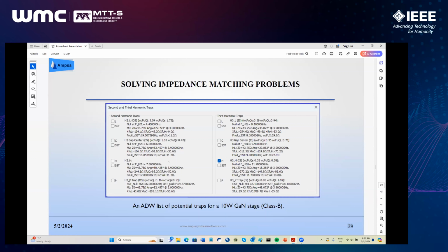So this is a useful table. I can at a glance say, I want to cover this frequency range. For that frequency range, I can have traps here. With these traps, I need these main lines to get what I intrinsically need for the mode I target. But what does it do to the fundamentals? With this table, you can answer that.